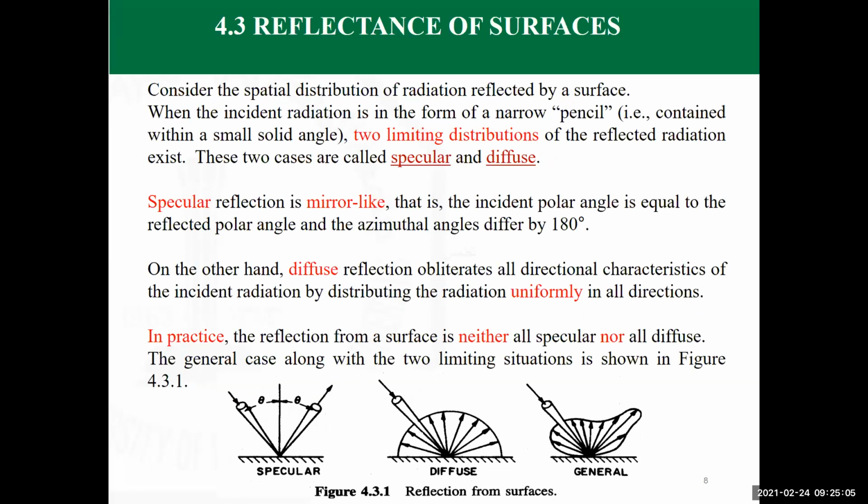Now, we are talking about reflectivity, the reflectance of a surface. It's a surface which looks like a mirror or a shiny surface, so that the energy falling on the surface is not used for heating the surface, but is reflected. And we are going to need this kind of property a lot when we are talking about parabolic trough collectors, for example, where your target for this kind of application is to have heating of a tube fluid. You have a fluid passing in the tube, and you need to heat it by solar energy.